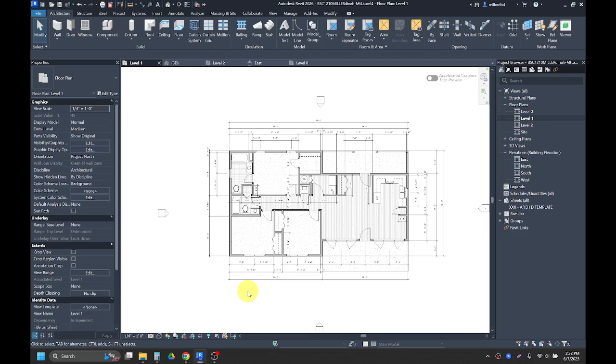And whenever we're making a building section, we want to think about, can we cut through where some openings might be? So just because I've made this building before, I know that a good building section I could do would go through around right here, because I can make it where it will go through this window, this door, and this window all at once.